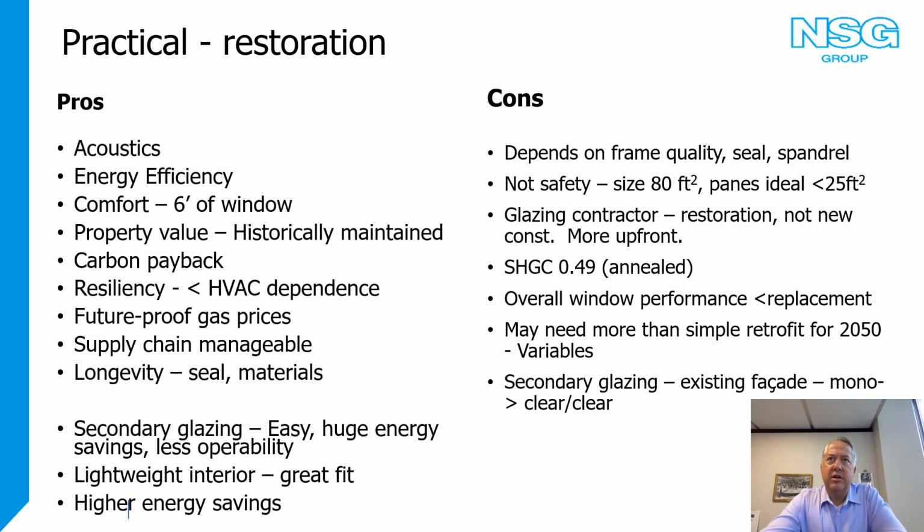In terms of your glazing contractor, a lot of the commercial glazing contractors that do the curtain wall systems or punch window installations may not be the same people that you end up using when you do a retrofit or a reglaze of an existing building. A lot of times you've got to have people that are knowledgeable about those historic materials. And you're also going to have the expectation of some more upfront costs when you're trying to get the right sizing and the right framing, and how do you clean it up, and if you have to do asbestos abatement. I mean, there's a load more stuff that goes into some of these retrofit systems.